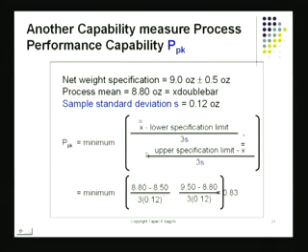Now there is a process capability index that goes even beyond this, and this one is called PPK. There is no real difference between what we've done before with our CPK and PPK. PPK basically looks at process performance. The only difference in the formula between PPK and CPK is, look at the denominator. The denominator of PPK is 3S, sample standard deviation.